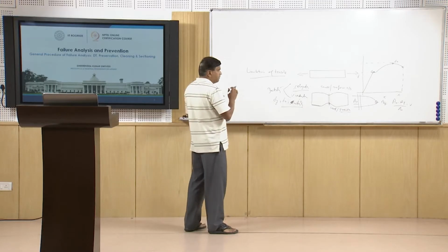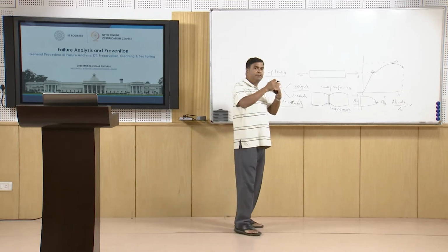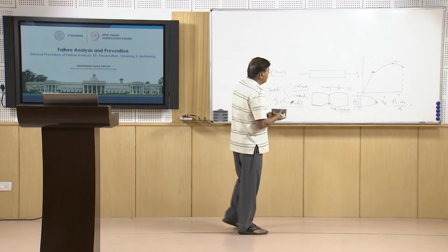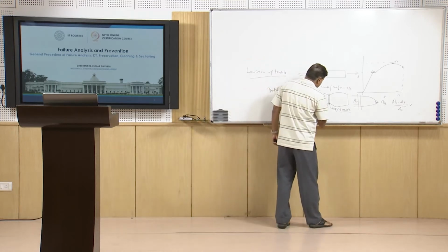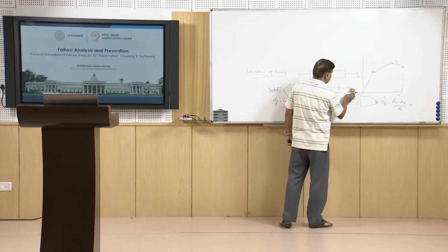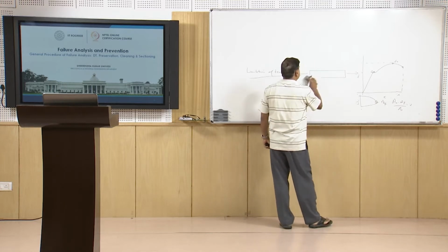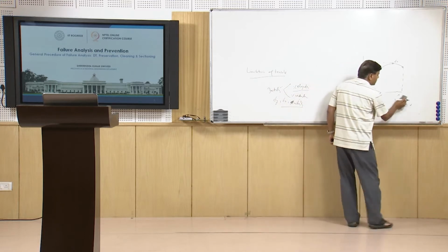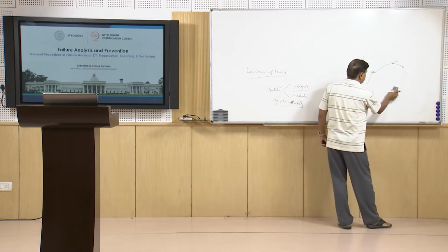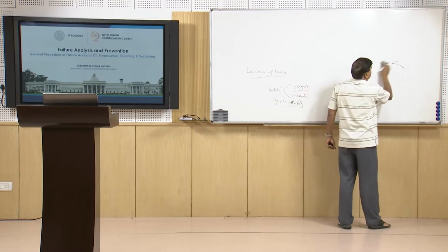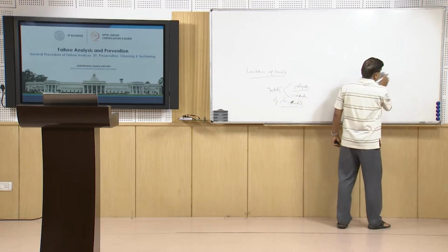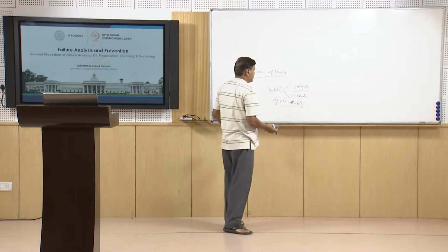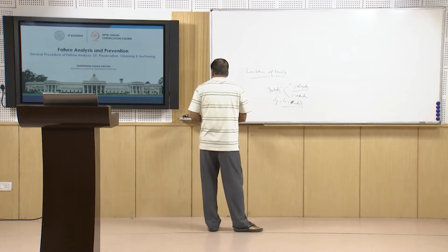But this is the behavior under a very low rate of loading, where the load magnitude is increased very gradually, while in actual service conditions failure rarely occurs due to deficient tensile properties of the material. Mostly failure occurs due to some other circumstantial conditions imposed by the service conditions, wherein tensile properties alone do not play a big role in the failure of the component.